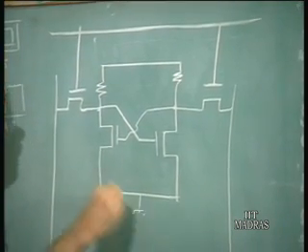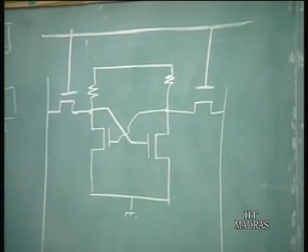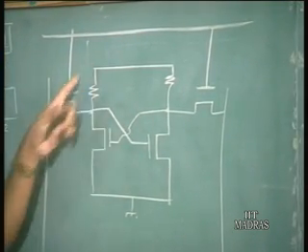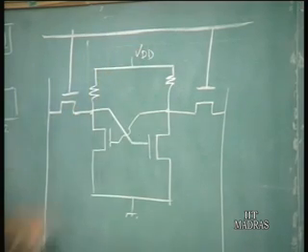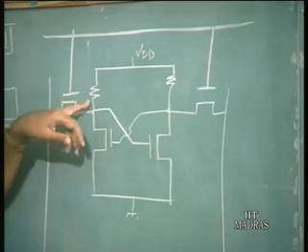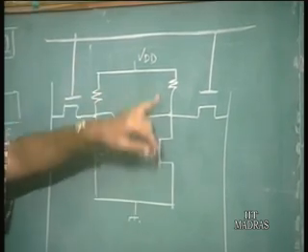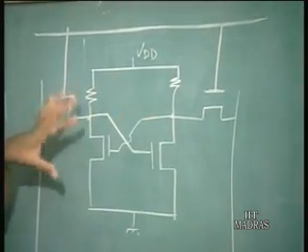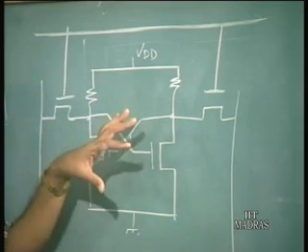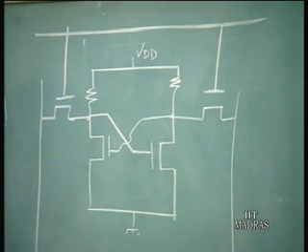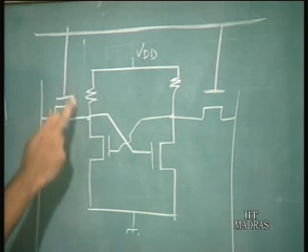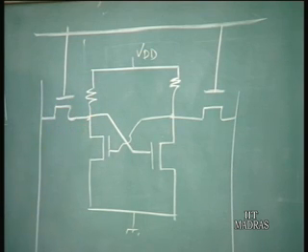What we see is that the inverter here is not the conventional CMOS inverter, that is, it does not have a PMOS load, but it has a resistive load. So, you basically have two inverters back to back, as in the case of a CMOS 6 transistor cell, but what we have is a resistance load. Now, this resistance is made of polysilicon, and undoped polysilicon can have very large resistances.